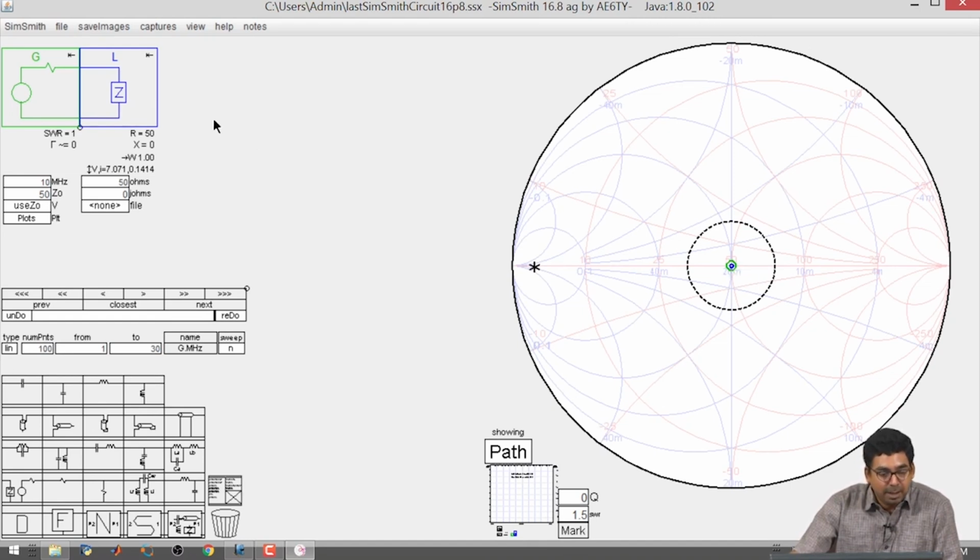The green part corresponds to the generating portion after the internal impedance, that is, you are looking in from this portion to the right side, and the blue part corresponds to the load impedance. Since the load impedance is 50 ohms, it is normalized with respect to the 50 ohms intrinsic impedance of the generator, and the resulting normalized load impedance is equal to 1.